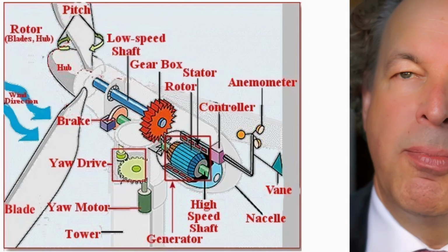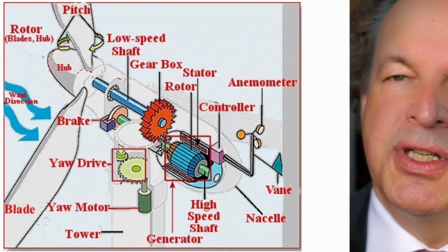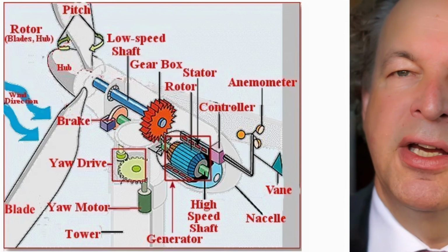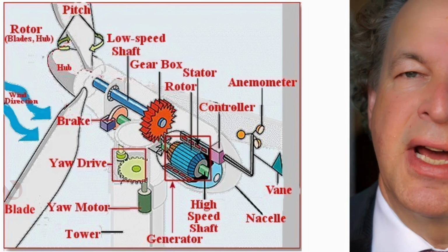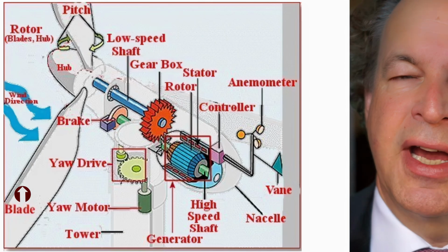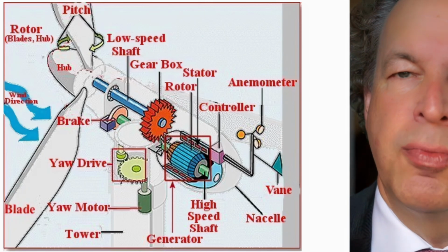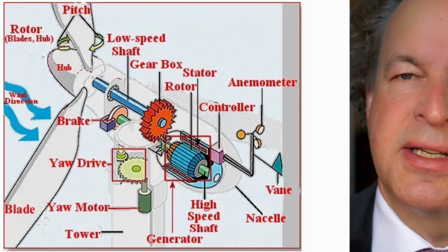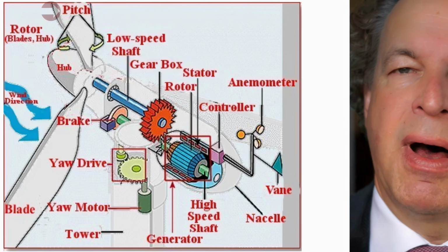Here you see the components of a wind power converter with a gear. More modern ones, which we see later, can work without a gear. The wind is captured by the blades. Then the blade has an aerodynamic form which creates a lift and is creating a moment to turn the turbine around the axis. You can adjust it at all modern windmills by the pitch.